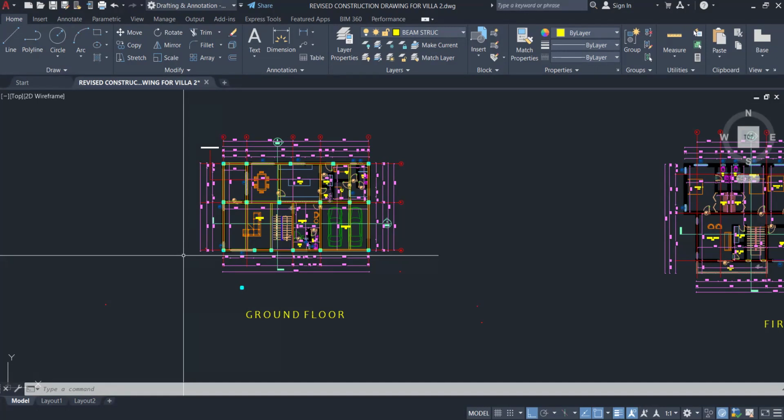My question is, is it a must that our beam should shoot out? No, it's not a must. I think we've discussed this in the previous class. Like the example we are working on now, we have a cantilever slab. We are going to see it. That's why I picked this example. In a void area where there is no block wall, you try as much as possible not to have your beam. It will not make sense to have a void and then have a beam running across it.